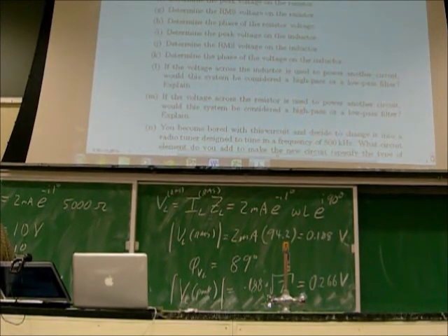Compared to what? We've said high pass and low pass. We've only said high and low. We never said high and low compared to what. Tell me philosophically, where is the point that you compare with high and low? This circuit is not resonant because it doesn't have a C in it. It only has an L. So what would I compare to find the frequency that I should compare this one to? On the power supply? No. Something about impedances, where you get the two of them equal.